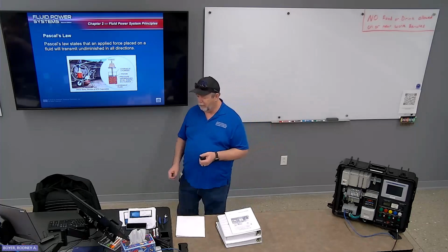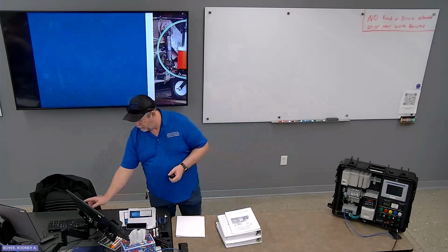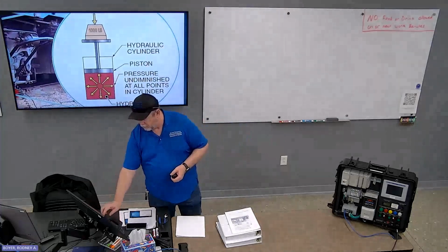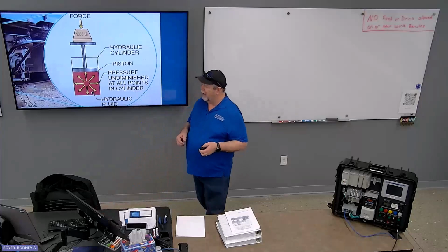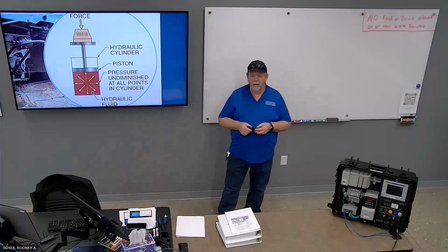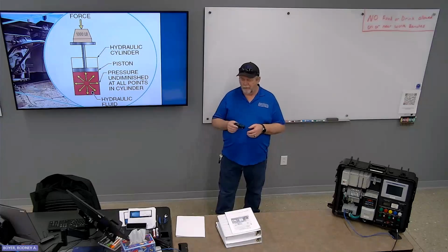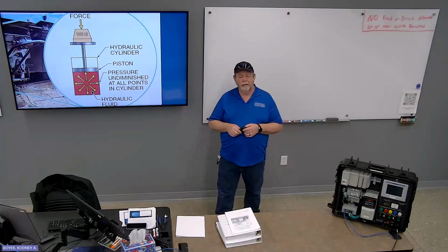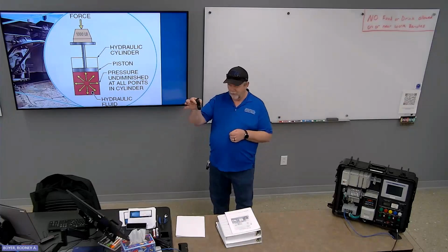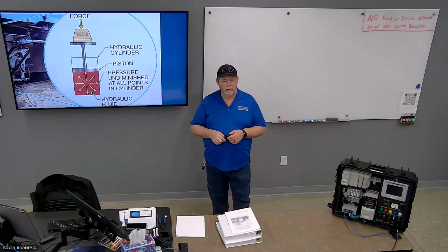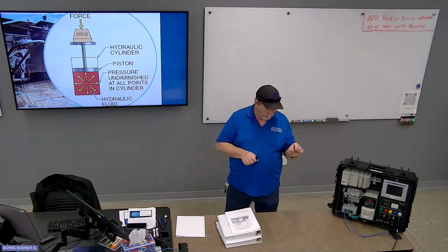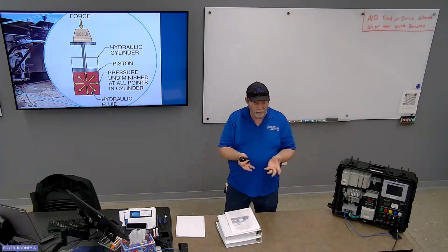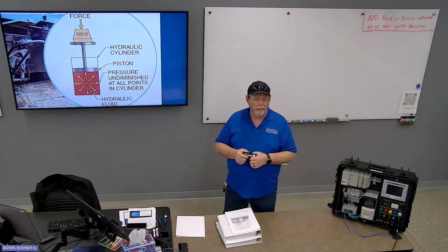So if I put 1,000 pounds on top of my piston, and I do not allow the fluid to escape from that cylinder, there's going to be 1,000 pounds pushing down. It's going to try and go in all directions. We're not just going to pressurize this little bit of fluid over here, we're going to pressurize all fluid that is in that vessel.